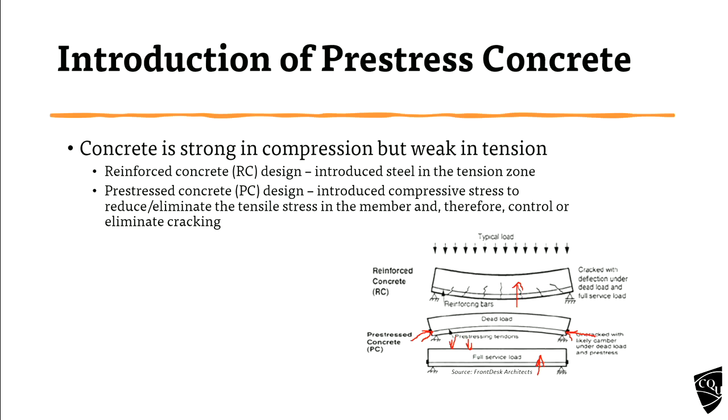The concrete, even though we said it can't take much tension, has some tensile strength, very small. So if you have small tensile stress, it can be carried by concrete, because the tensile strength of concrete is not zero. For the ultimate case we take it as 0, but for the serviceability case it will be some value, maybe 5 megapascal or 10 megapascal.